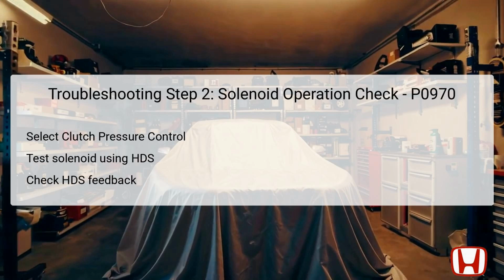For troubleshooting step 2, the focus shifts to the operation of AT clutch pressure control solenoid valve C. Using the HDS, select the clutch pressure linear control solenoid valve C under the miscellaneous test menu. Once selected, the HDS will allow for real-time testing of the solenoid's functionality. After initiating the test, monitor the feedback provided by the HDS.